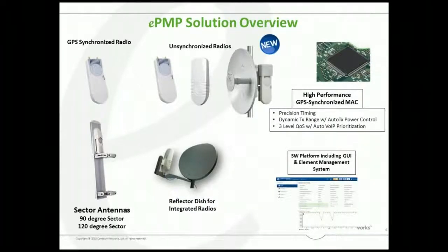And the radios are based upon an 802.11n chipset, which is a Wi-Fi chipset that helps us maintain a low cost. And while it's based on Wi-Fi technology, it is not actually Wi-Fi. We've completely rewritten the software at the protocol layer called the MAC layer, which is something that needs to be done with Wi-Fi based solutions when you want to deploy them in wide area outdoor scenarios. In addition to that, we have a graphical user interface that helps you manage and monitor the system, as well as an element management system that's available for download free from our website to manage the whole solution.